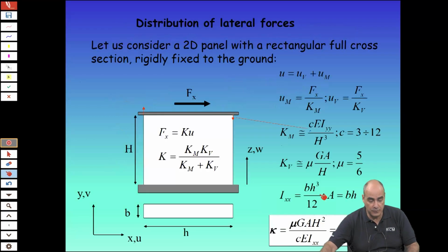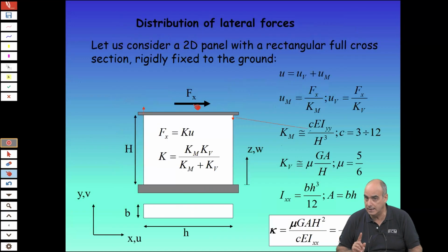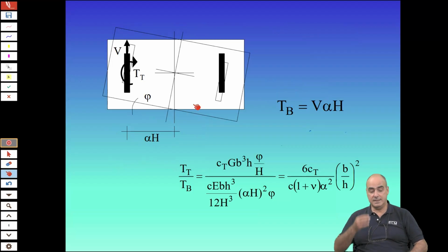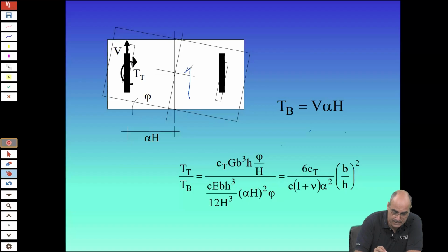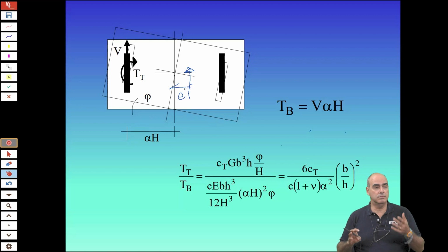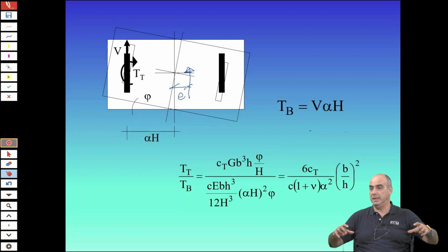It's another case if you have elements like this. The torsional stiffness here cannot be neglected. But in walls, you can neglect it. But imagine that you have a system like this, and imagine also that your force is applied here with an eccentricity E. There can be different reasons, but we also always consider a tolerance equal to 5% of the side of the building.